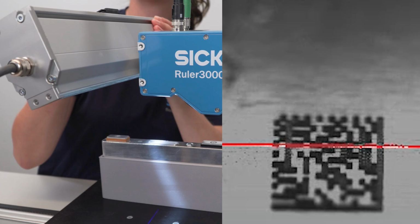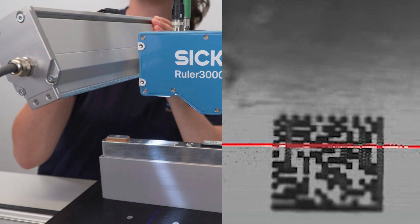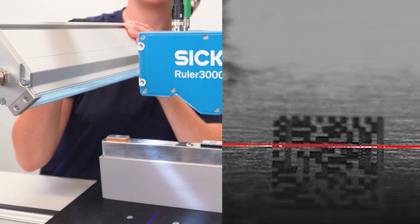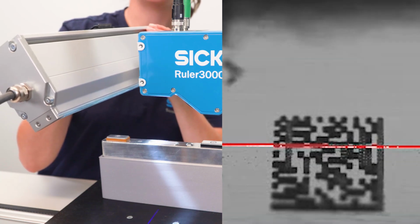To achieve a specular geometry, aim the light towards the laser and start with a slightly steeper angle close to the camera. Then increase the angle and move the light slightly away from the camera. We can see that the light gets brighter and brighter until it gets darker. At this point, move back to the position with the brightest light, and here you have found the perfect specular angle.